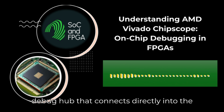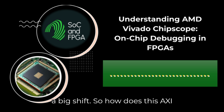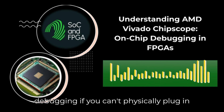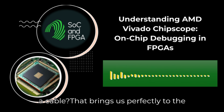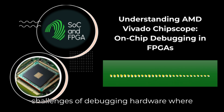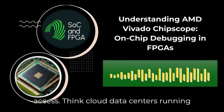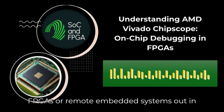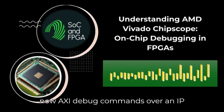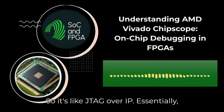Versal uses an AXI debug hub that connects directly into the system's main AXI infrastructure. That's a big shift. So how does this AXI approach affect things like remote debugging if you can't physically plug in a cable? That brings us perfectly to the Xilinx Virtual Cable, or XVC. This is designed specifically to address the challenges of debugging hardware where you don't have direct physical JTAG access. Think cloud data centers running FPGAs or remote embedded systems out in the field. Okay. XVC is basically a protocol that tunnels JTAG commands, or now AXI debug commands, over an IP network, Ethernet, PCI Express, whatever. So it's like JTAG over IP.